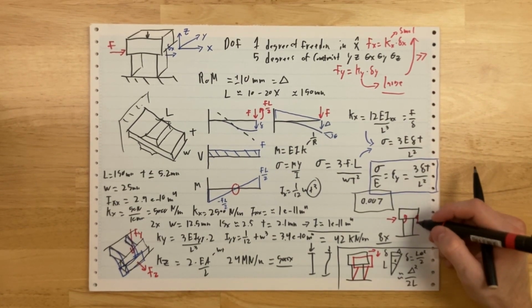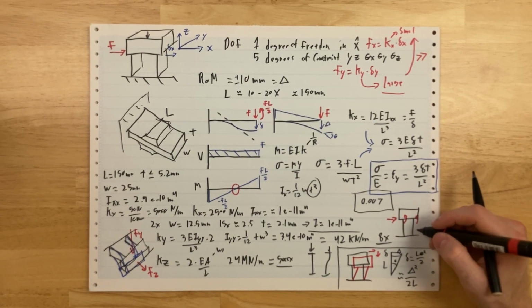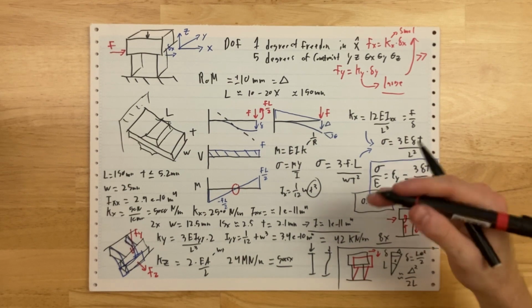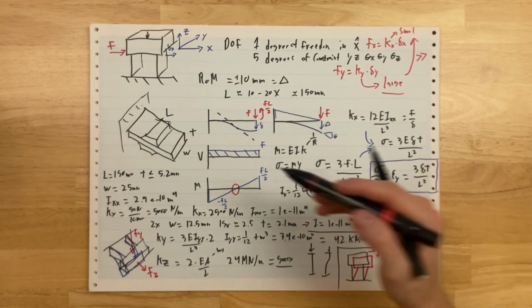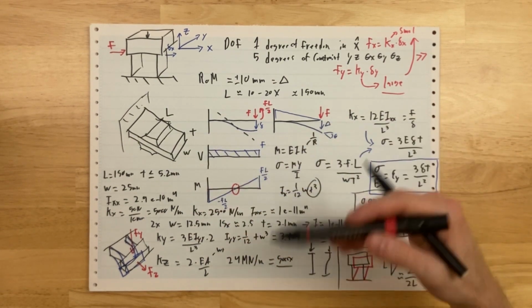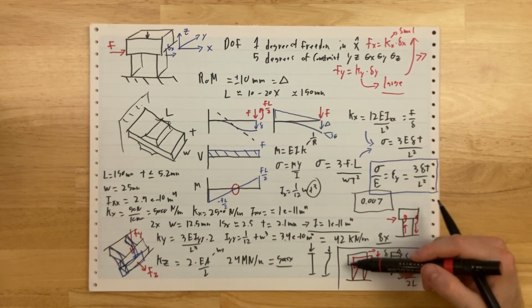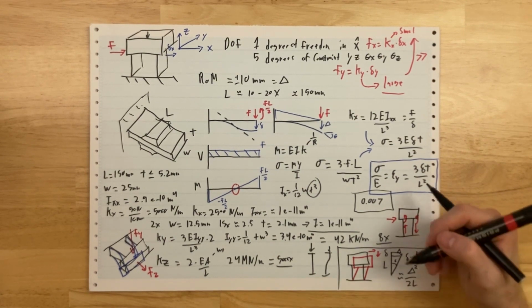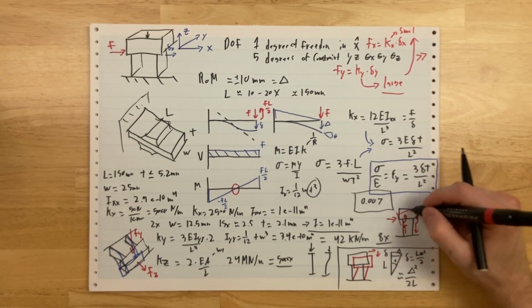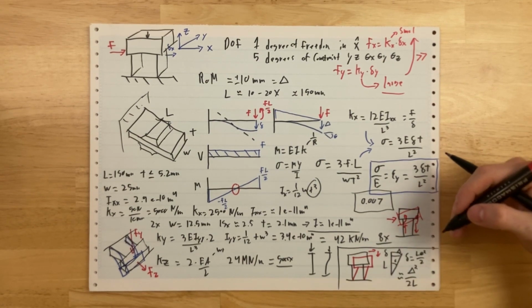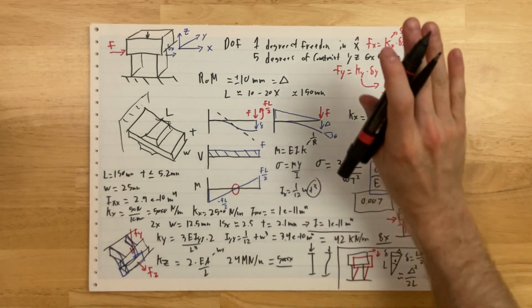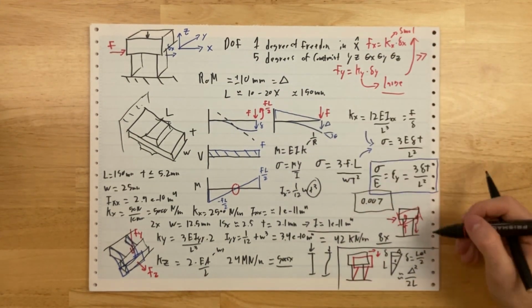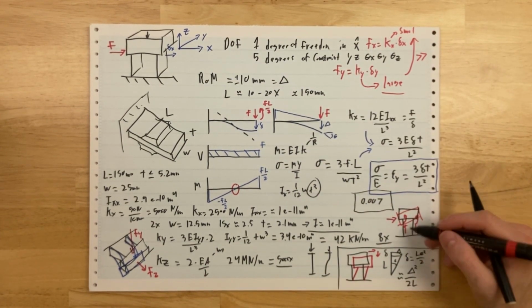Well, there's actually parasitic forces in the legs. This leg has to pull down, and that leg has to push up in order to keep the bar from spinning. So now you have a parasitic z-force in your blade, which gets resisted by the stiffness of the blade in z, which is pretty high, but again, falls off with motion. And that results in small deltas, and essentially this whole bar is actually pivoting, it's actually rotating. So as you're pushing it, not only is it sinking down in a shallow arc, it's actually rotating upwards too. There's multiple parasitic motions. And actually, how do you get rid of that?